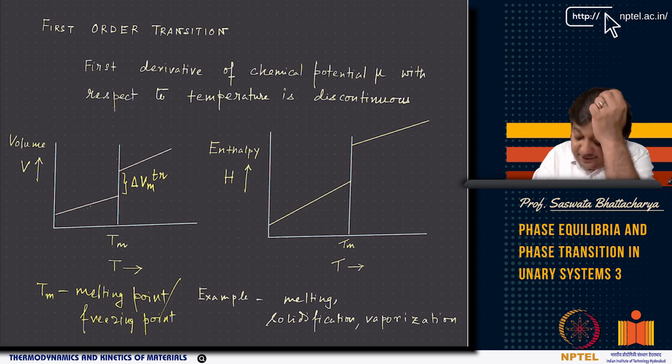Similarly for enthalpy, see for example here, so from some temperature at start, now in this case what I am talking about is like a delta H equal to Cp dt. So here we can think of this as Cp dt. Now once you have reached the melting temperature, there is no sensible heat, there is no Cp dt, there is no rising temperature, right? So basically what has happened is you are at Tm, but now you are changing the phase, that is from solid.